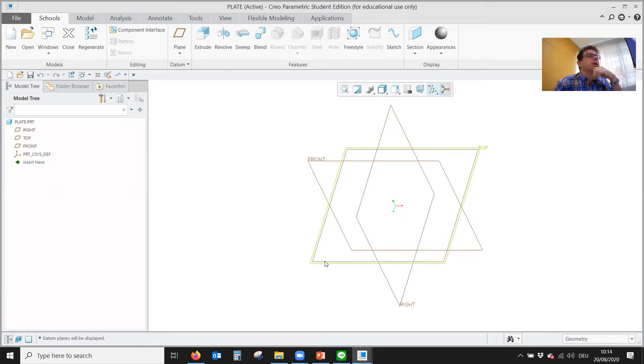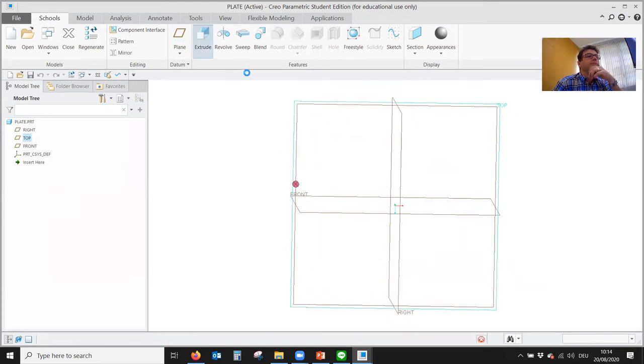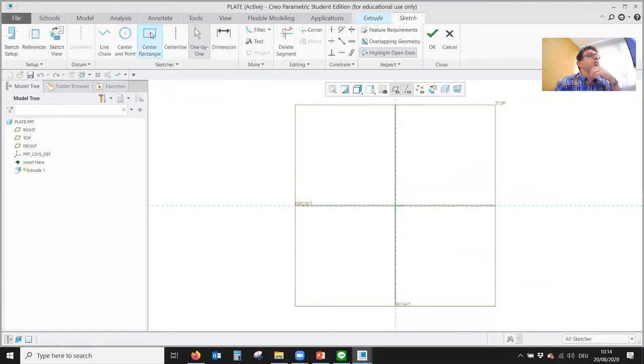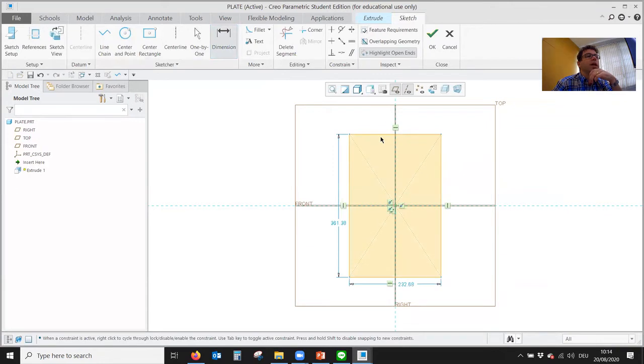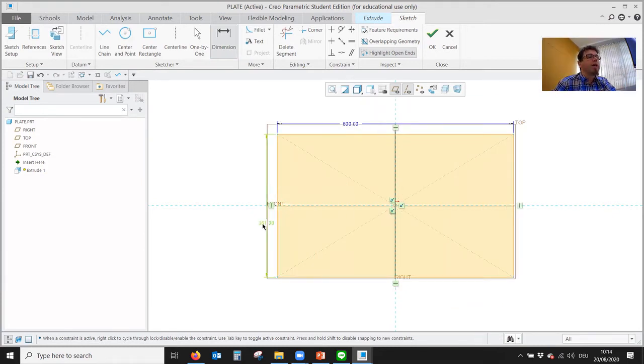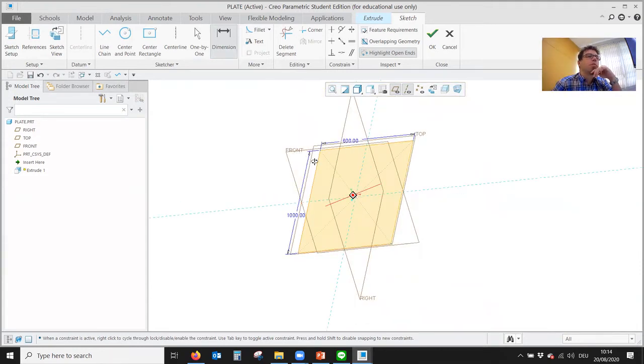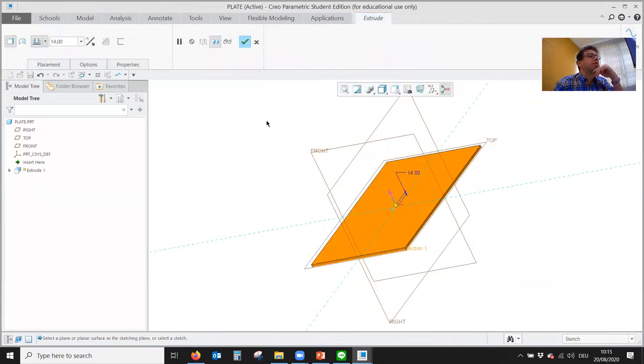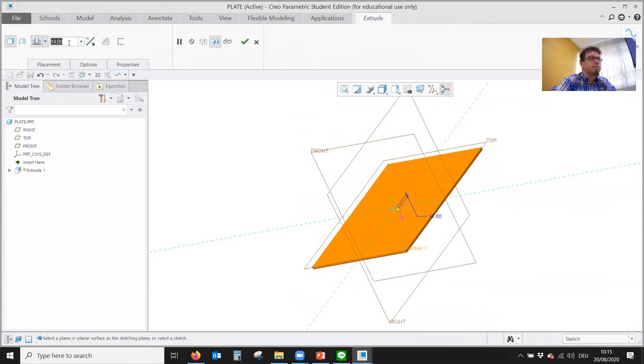So I will just make an extruded shape here. It will be symmetrical. I haven't yet figured out how to change the menu again. So that's going to be pretty large, maybe 1000 by 600. I don't know yet. So I'm improvising here. 1, 2, 3. So that will be the plate, 1000 by 600, and I'll make that maybe 50 thick. No big deal, that was easy.